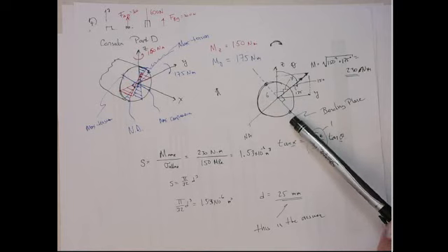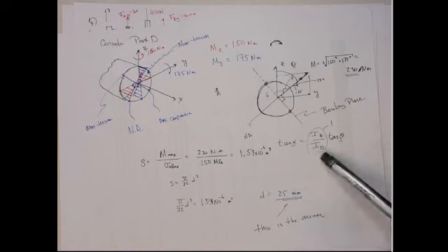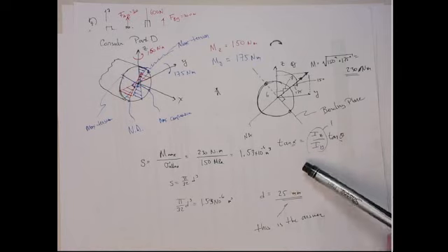All right. Now, since this is a symmetric cross-section, Iz and Iy are equal, the location of the neutral axis is going to be perpendicular to the bending plane. For an I-beam, that would not be the situation necessarily, okay?